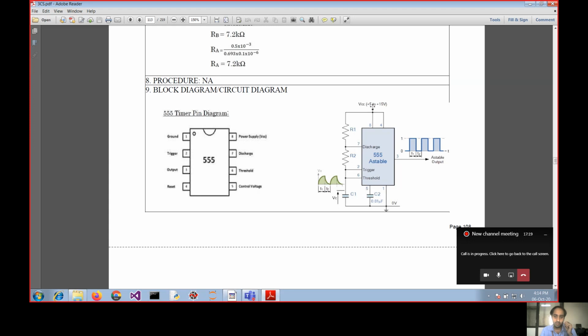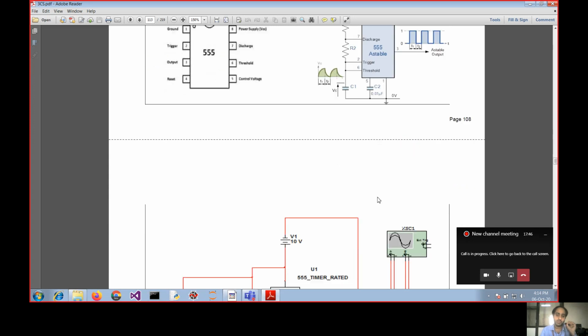Anyhow, here we are applying plus VCC, which is completely DC voltage, but apart from that, a little bit of AC voltage will be there. To avoid that kind of noise, we will bypass all the AC signal through the capacitor and everything will be grounded, so that we only see the DC voltage in this circuit. For this we are going to use the bypass capacitor C2.